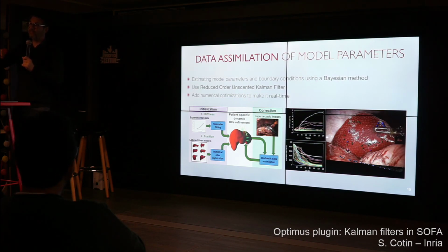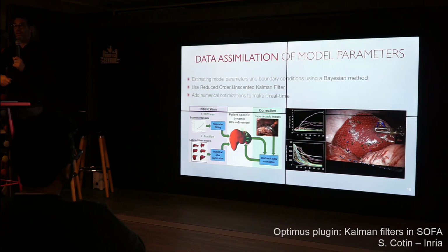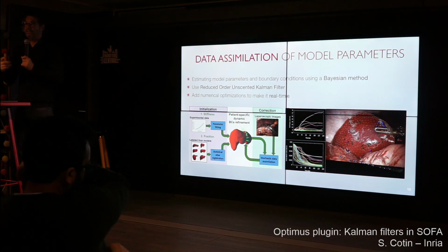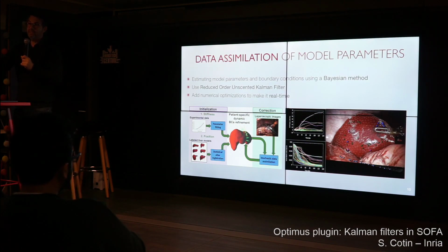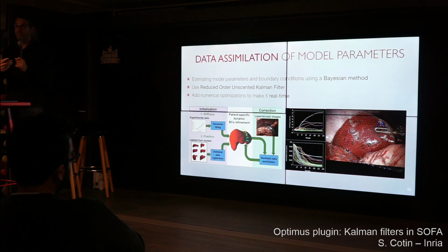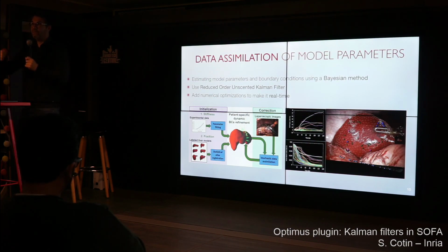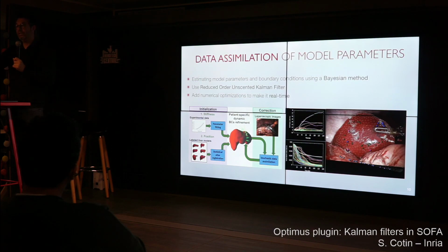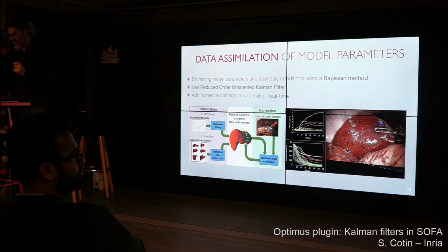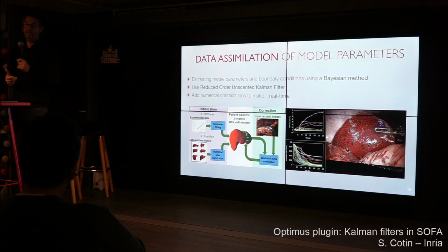So we create lots of springs. In our case, they are nonlinear springs that describe the possibility that here there's a connection to some other structure. And the algorithm, by looking at those videos, will estimate the stiffness of the springs. And if there is no boundary condition, it will set a very low stiffness, meaning that it's free of motion. And that actually also works well. And when we do that, for instance, we can get simulations that are much more accurate than if we don't account for those unknown boundary conditions.